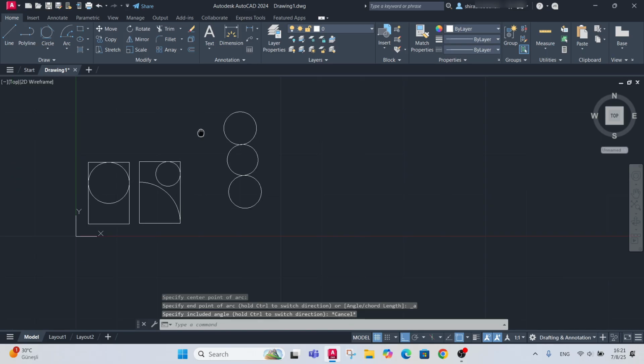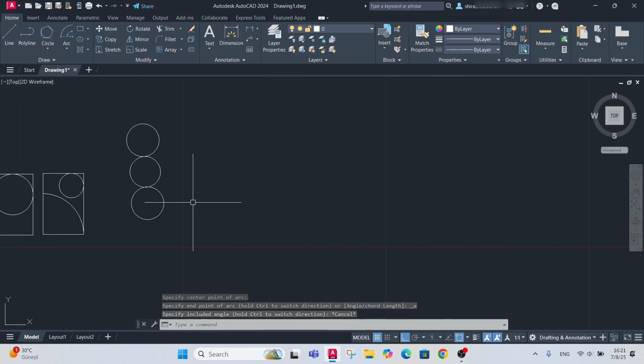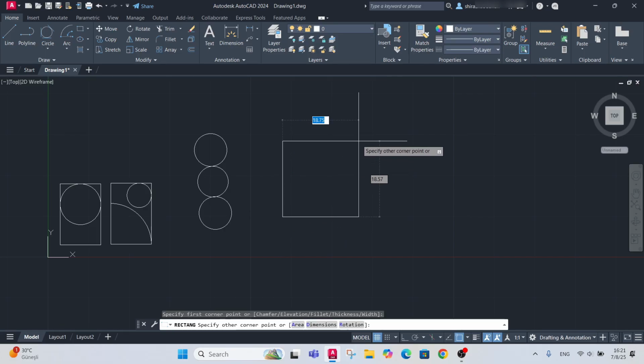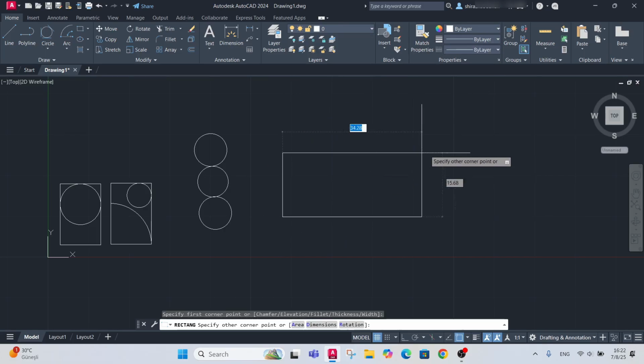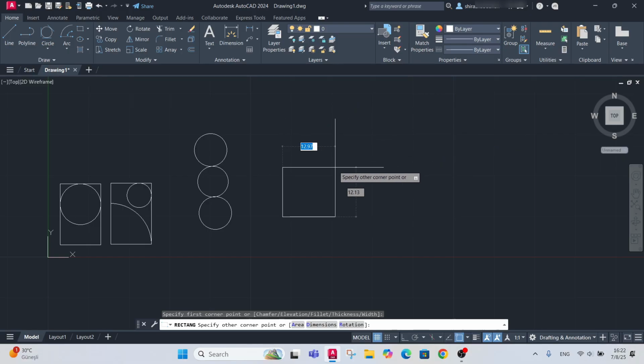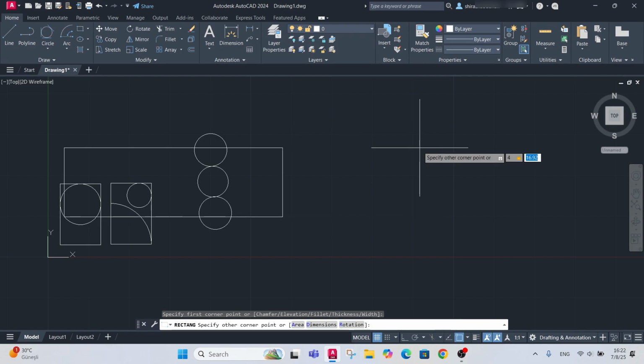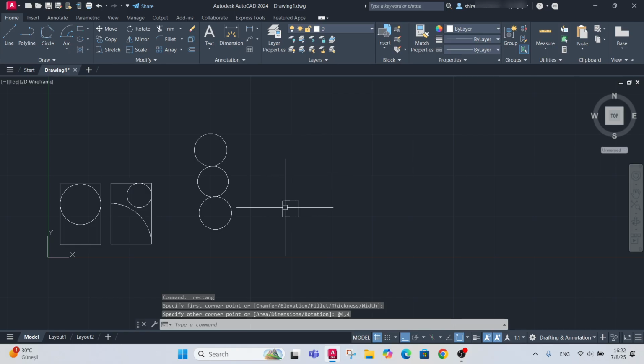Let's go on. So the shapes are coming along well. Just for an explanation, now there's a rectangle. Just snap it. There are two ways of drawing a rectangle: you can use coordinates or you can use dimensions. If I want to use coordinates, I will type maybe 4,4. But 4,4 automatically means x positive, y positive. When I hit enter, it will draw it to the top.